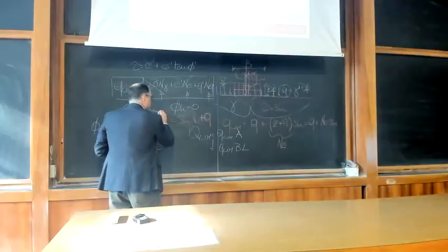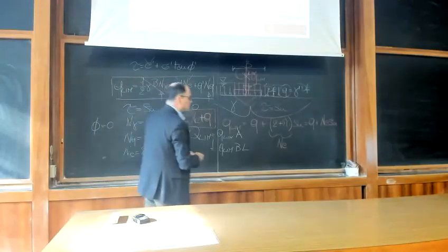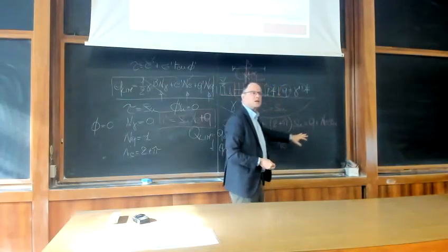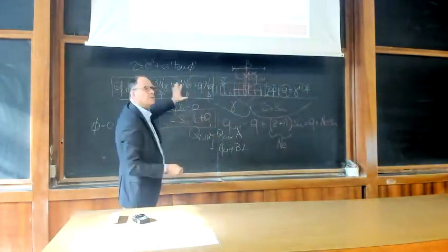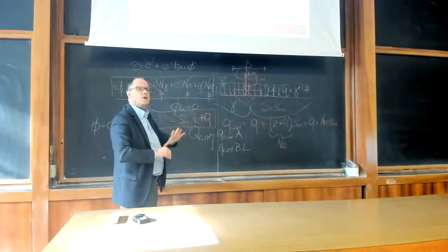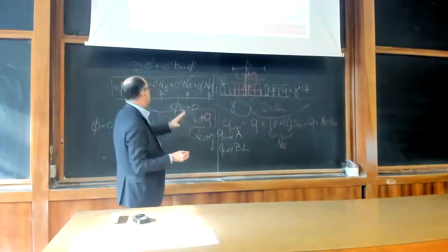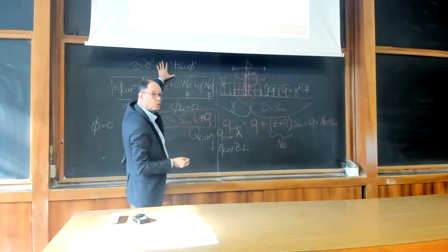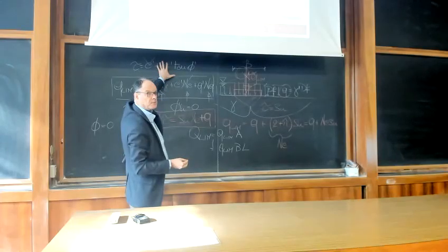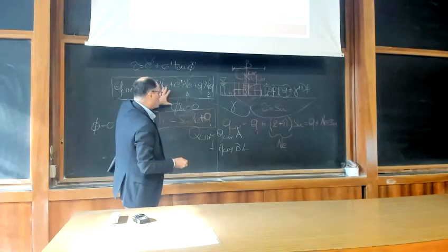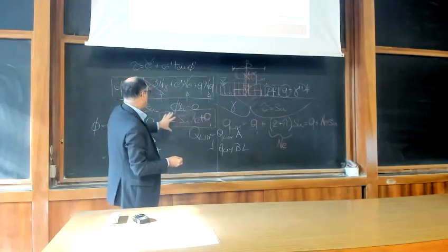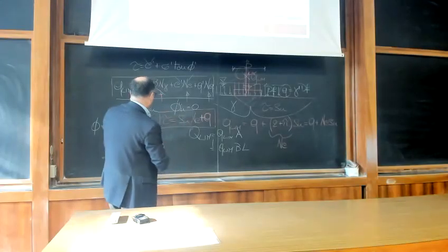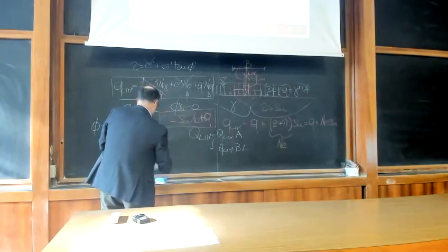And so you end up with an expression which is exactly what we had already determined using the plasticity theorems. So this expression, these three terms, are of general validity, can be applied in drained conditions if you use the Mohr-Coulomb criterion and the Mohr-Coulomb shear strength parameters, and can be used also in undrained terms if you use the Tresca criterion, sorry, this is not tau, this is killing me, of course.